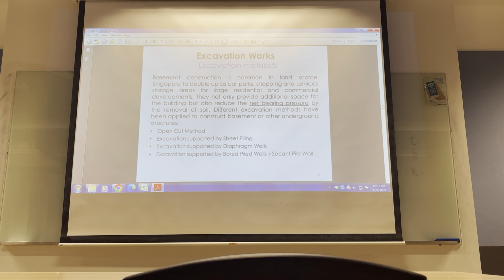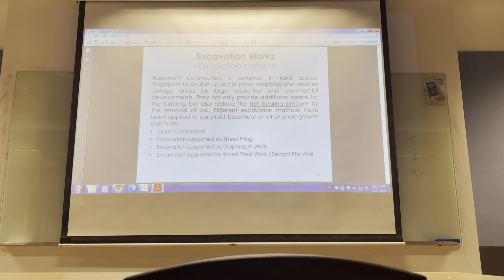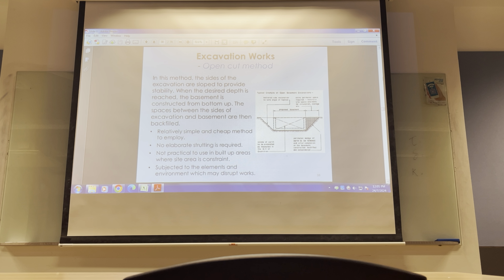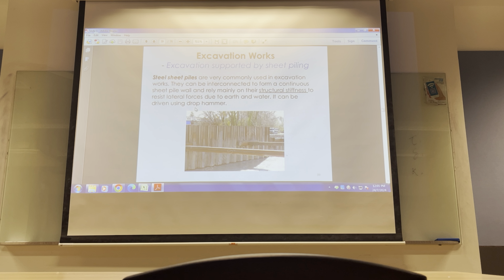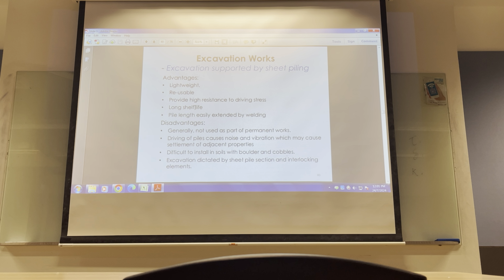Then, for your basement construction, decide what type of excavation method can be adopted there in that sort of ground, in that sort of layout, and you proceed with the design of that temporary work. Temporary work on an open cut required to be studied is the slope. Your slope needs to be designed. You cannot anyhow cut any angle. You can use sheet pile if your soil is soft enough.